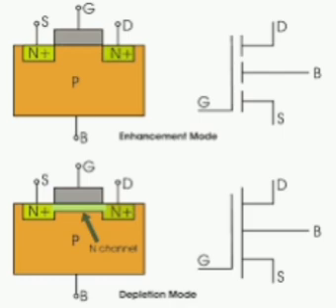Forward voltage across diode decreases with the temperature. For 1 degree centigrade rise in temperature, it decreases by 2.5 millivolt: dV by dT equal to minus 2.5 millivolt per degree centigrade. I naught equal to A Q Ni square into (Dp by Lp Nd plus Dn by Ln Na), where A means area of cross section, Dp and Dn mean diffusion constant of holes and electrons respectively, Lp and Ln mean diffusion length of holes